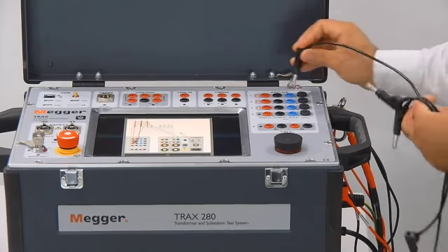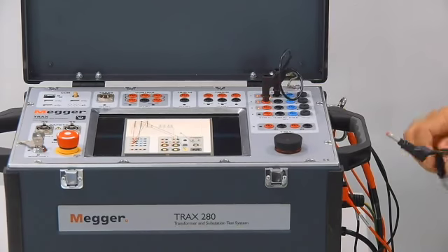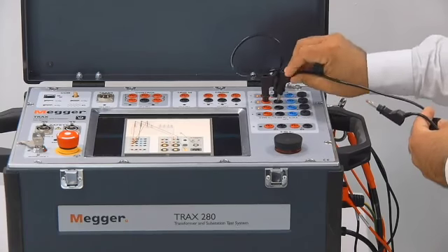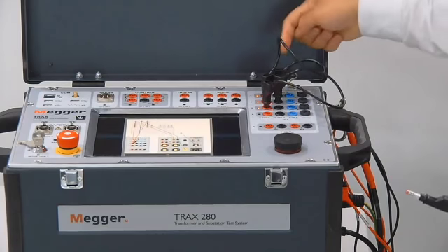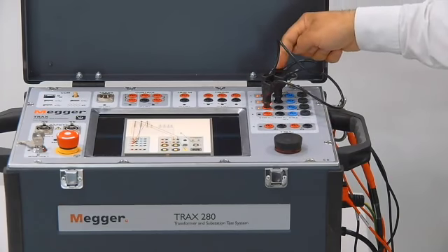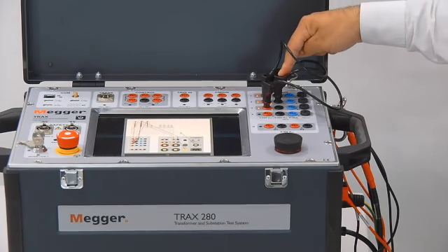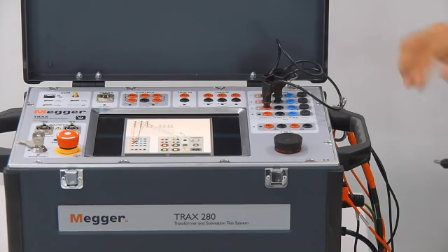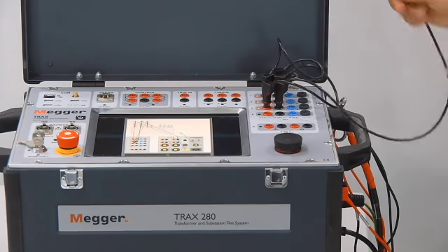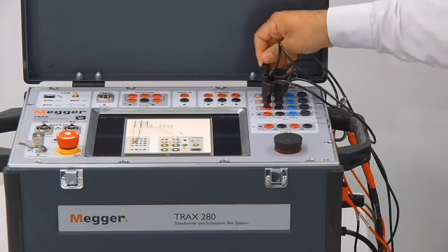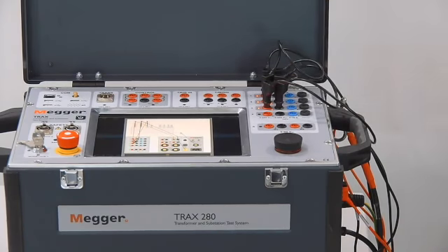I will first do what we call delta preparation. I have these little jumpers helping me: black of channel 1 connected to red of channel 2, black of channel 2 connected to red of channel 3, and last, black of channel 3 connected to the red of channel 1. So I have phase 1, 2, 3, but there is a delta loop in the picture.